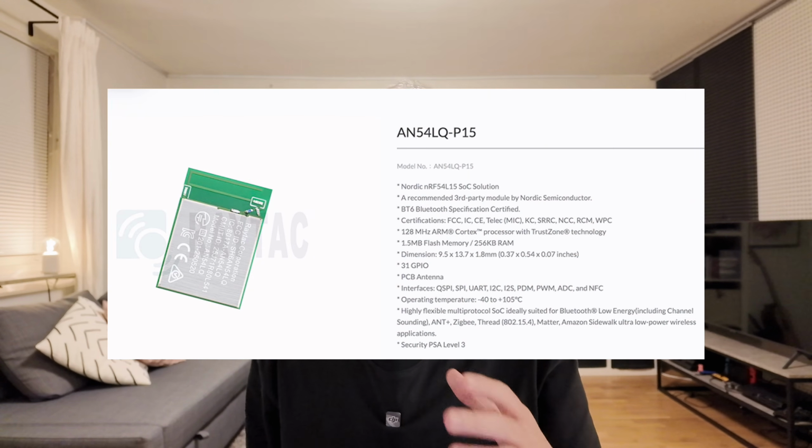And I've selected a module from this company called Raytac. So basically what they do is they take the nRF54 and they wrap it into a module. They design the PCB antenna into this module and they pre-certify it. In case you didn't know, certification is expensive.